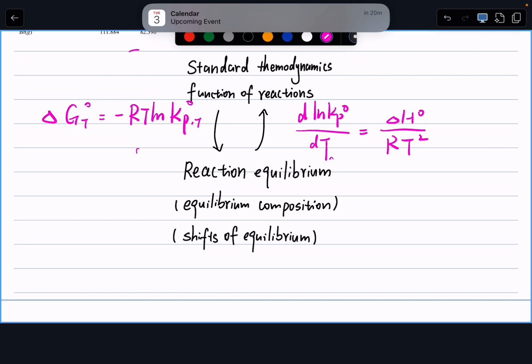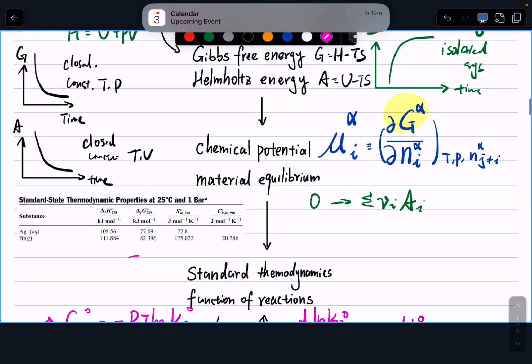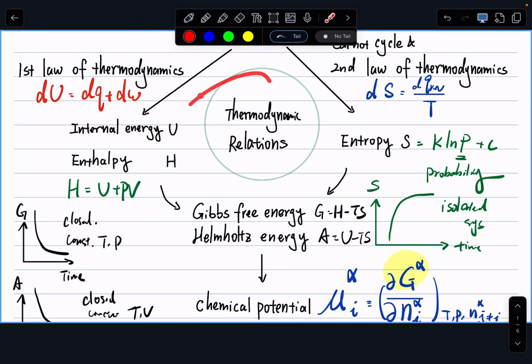You see, even if things are sort of remote, we are using things we derived before, like the one we did, the one component phase diagram, right? You have 3 points connected to each other. We can ask you to derive the relationship of Gibbs free energy as a function of temperature for those 3 points. And that is using these equations we derived before. So hopefully this gives you, well, I guess not an overview, a summary of whatever we discussed together in this entire quarter.